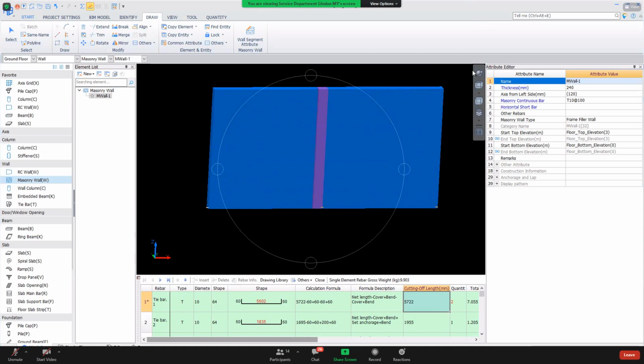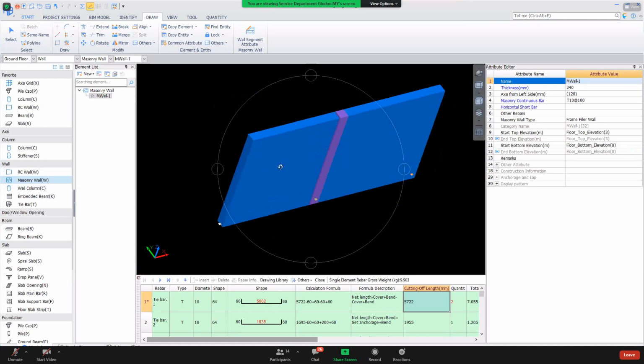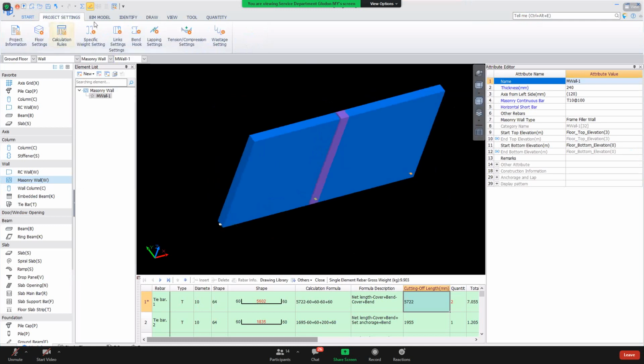We don't want it because usually this type of wall, the reinforcement will be at the bottom. For those kind of general notes that I've seen before, it's always at the bottom one. And I only see 2 at the bottom part. You have 2 horizontal bars at the bottom part. The top part usually won't have reinforcements even. Right? So that one is for the filler wall.